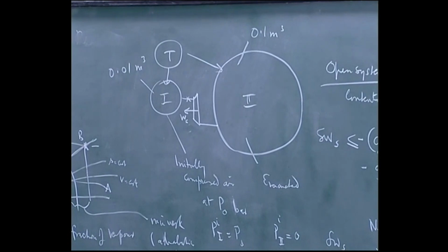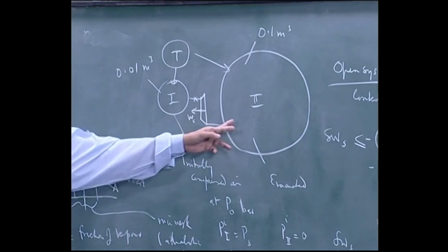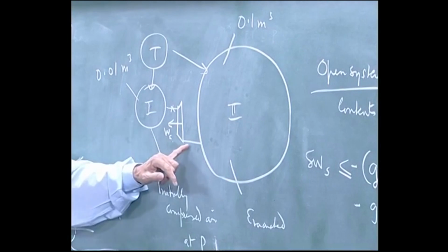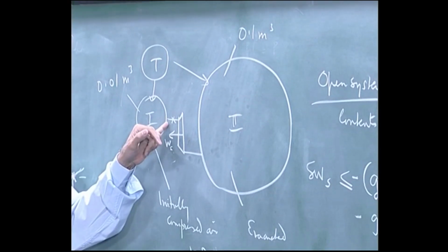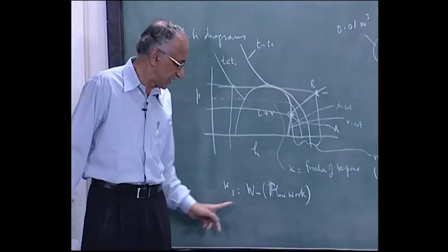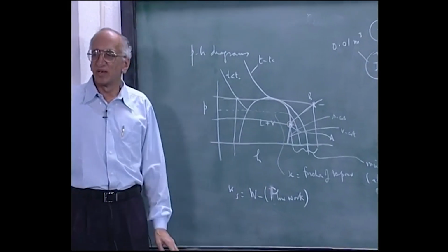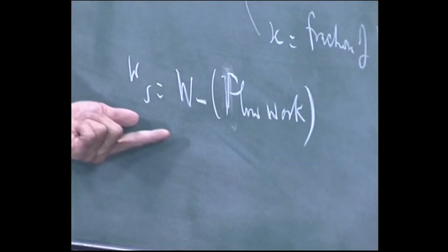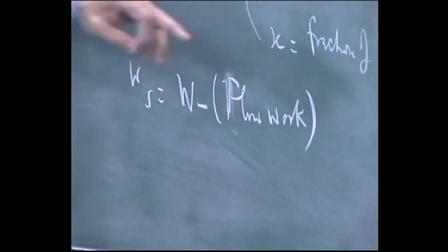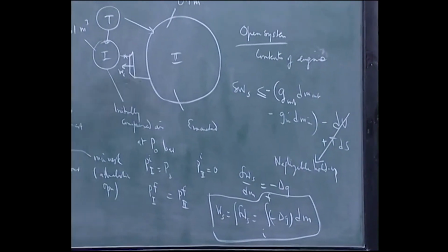Normally if it was an ideal gas, for example, PV would be RT regardless of the state. The pressure and the volume change, but PV is RT. So in an isothermal operation the work out will be the same as the work in. So for an ideal gas there will be no difference at all, flow work will be 0, Ws will be equal to W. In many cases flow work is negligible, so Ws will be approximately W, but we can calculate that exactly. I will do this other calculation, then it will become clear as to what we are talking about. Is that calculation clear?